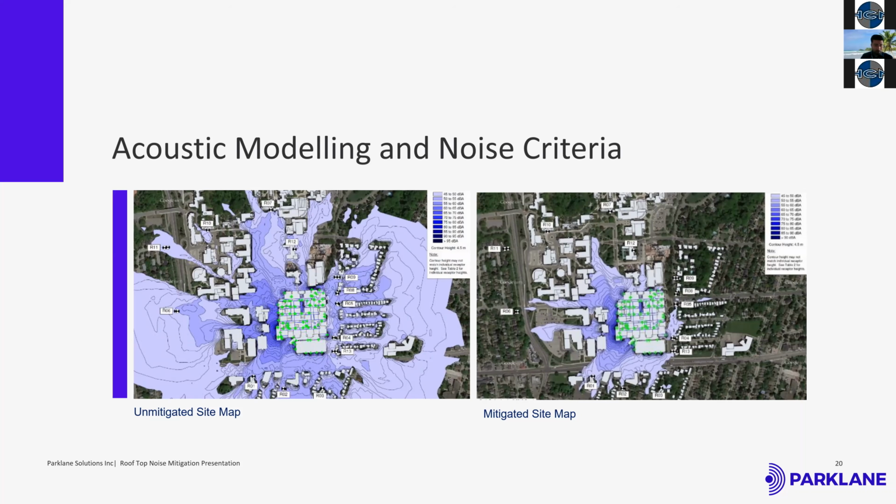Based on what the noise levels and noise sources are, the mitigation type will differ. For instance, it could be an acoustic barrier, but all that criteria needs to come from an acoustic consultant, especially when there are multiple sources, so that all criteria is met at each individual receiver location.